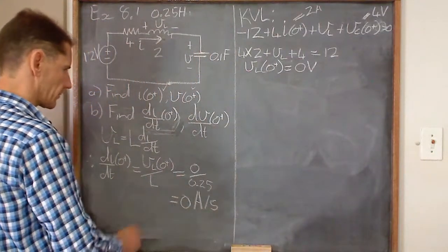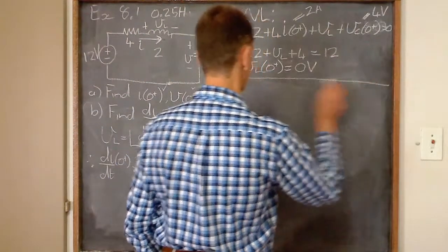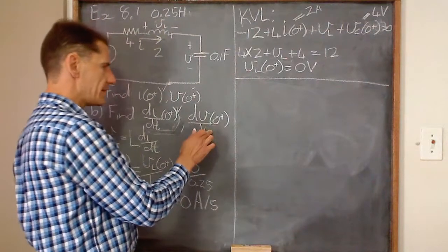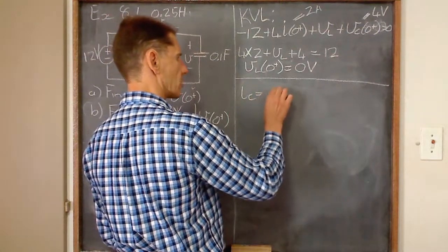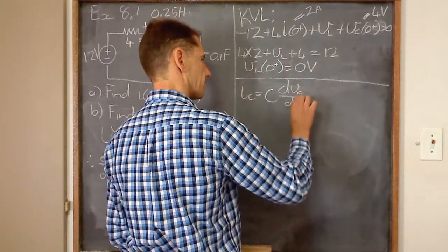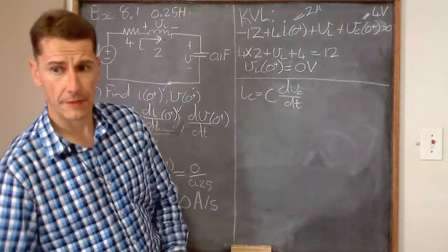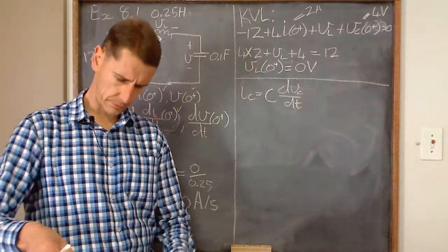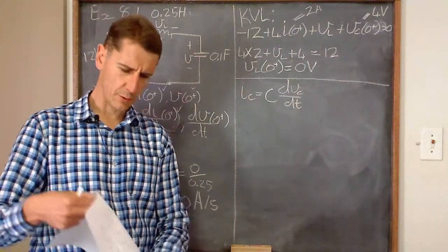Okay, so that sorts out the dI/dt. So now we've got that one. Now we need the dV/dt. So how do I get dV/dt? Again, chapter 6 actually. So we know the current through a capacitor equals C dVC/dt. Right, so that's from chapter 6. So you actually still need that theory, lo and behold. Let me just page over. My fingers still want to grip a chalk. Okay, there we go. So here's the dVC/dt.